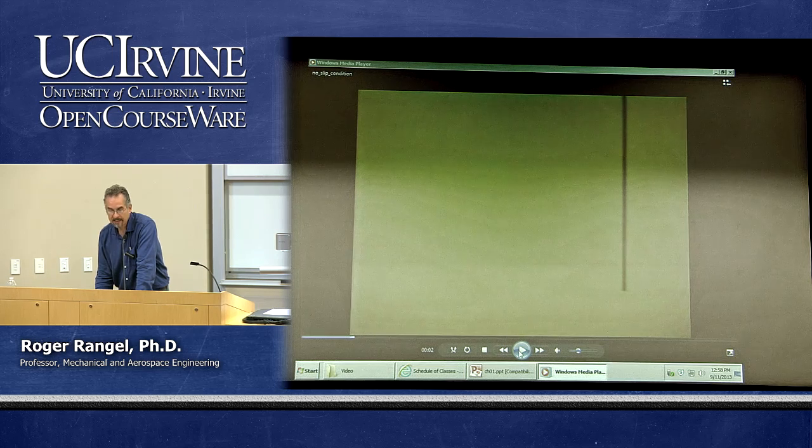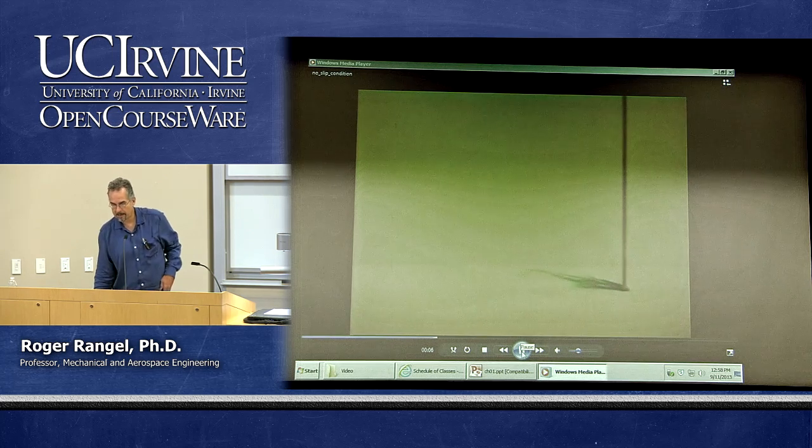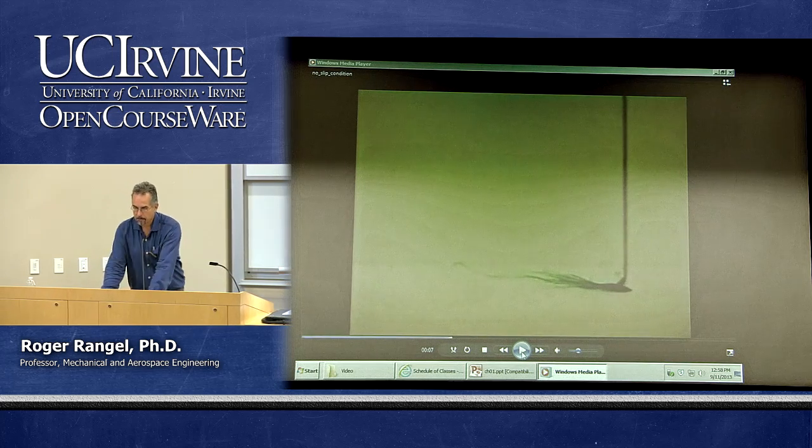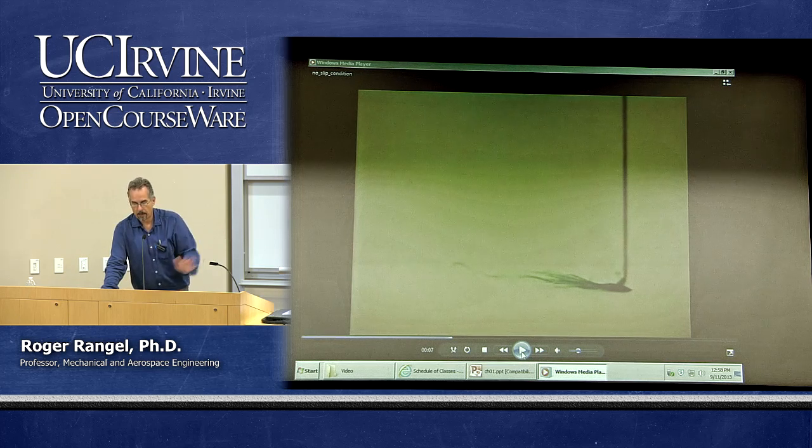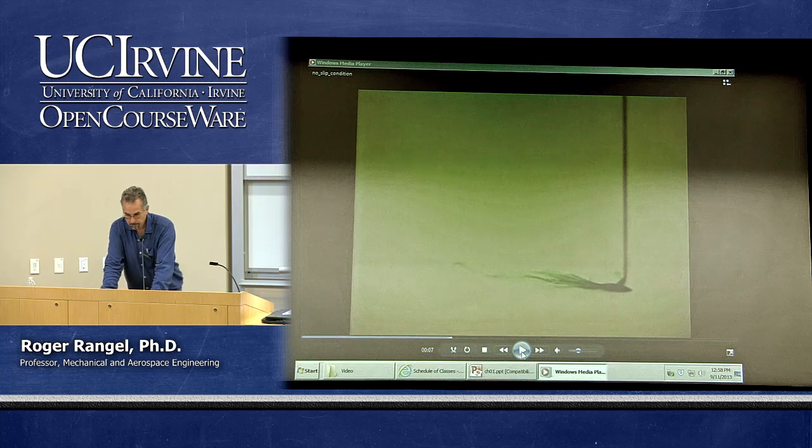So right now, the probe is at the very bottom, so it's very close to the bottom wall. And when you release the marker gas, you can see how it actually stays stuck to the plate. It doesn't move from the bottom of the plate. There is a portion of the fluid that does travel away because of the gas, because it rises a little bit and it catches up with the fluid that is able to move because it's not stuck to the wall.